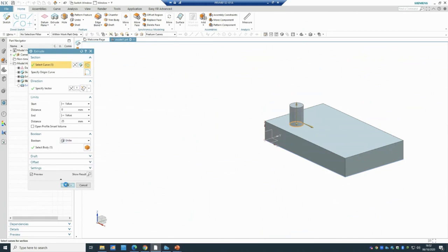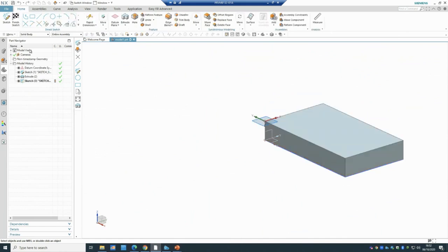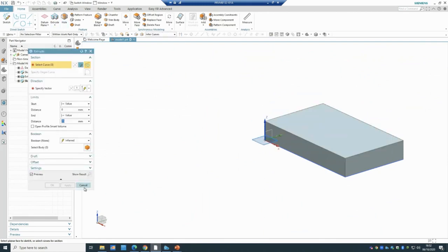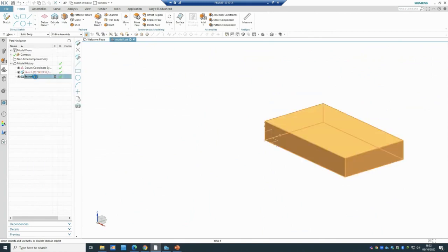file. And now if I go to here, and go with the filter, I want to go with solid body, I would have one solid body, whereas previously I had two solid bodies. So these are booleans. Don't worry about it. This is something we'll put under practice in future, but it's good to know. But now let's go back to the normal extrude, and I'm gonna talk about the different options we have in the extrude.